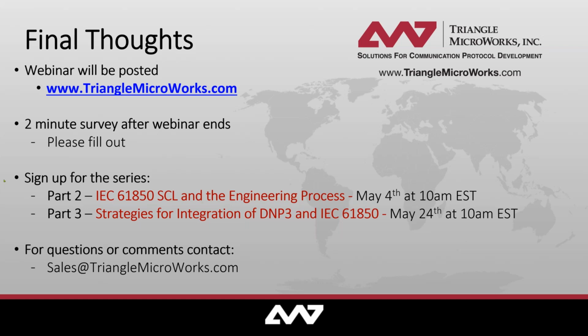I can answer. There is no standard mechanism in DNP3 to exchange information directly between devices. As it has been stated in one of the responses, we have systems where users are using GOOSE together with DNP3 to perform that functionality. In other cases, it's still wired. And we will discuss this a little bit in webinar 3, the possibility to use GOOSE in parallel with DNP3.